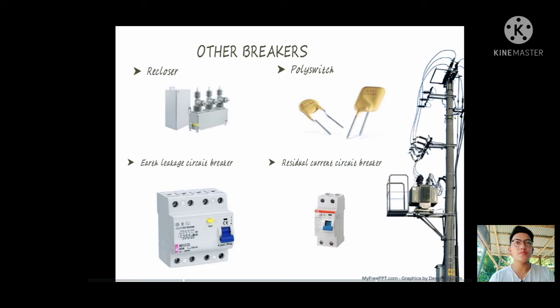So for other circuit breakers, we have a recloser. Reclosers are used in overhead electric power distribution systems to prevent short duration faults from causing a sustained outage.